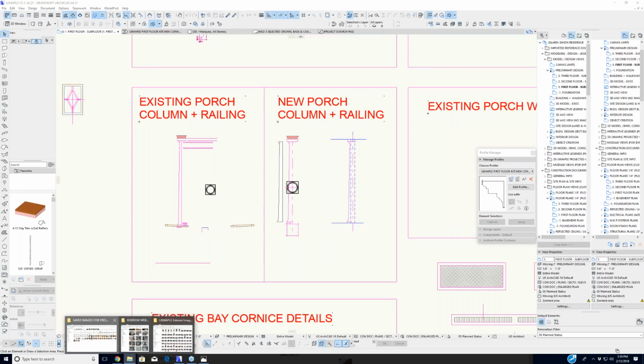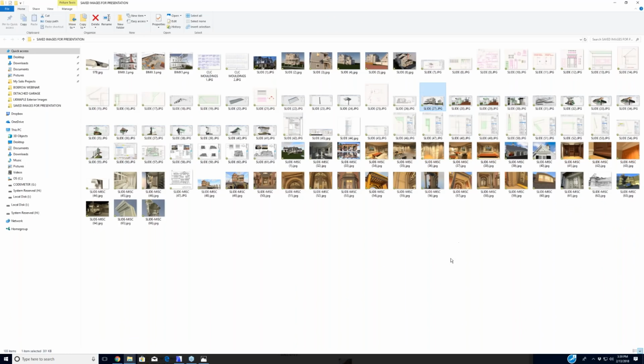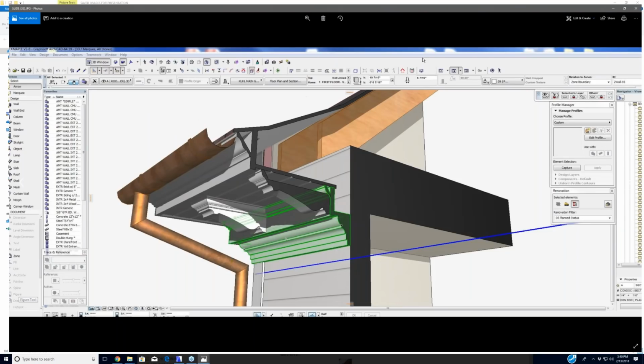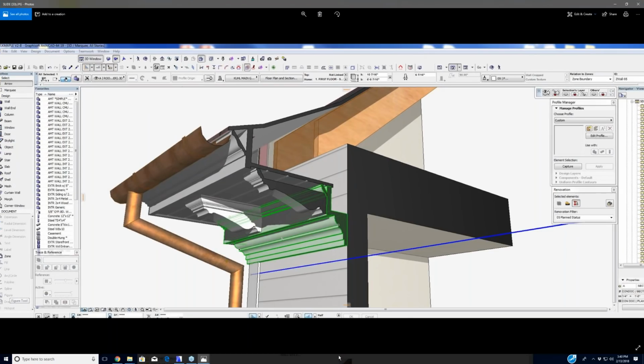I think what I have in here, I could show... let's say something like this, where I'll do screenshots all the time, and I'll send that directly to the builder really quick, even on the phone. He might say, is this rafter sitting on a top plate? Is this projecting out? What's the spacing of these modillion blocks? If it's modeled correctly and you put up your time, when this is under construction, I'm not recreating this or spending time trying to get them that information.